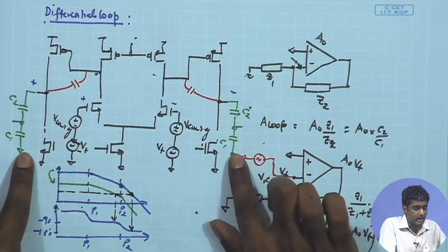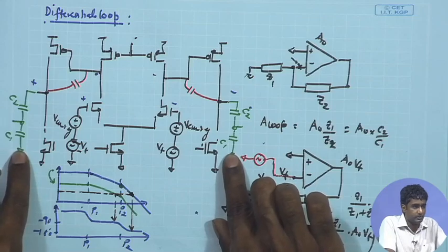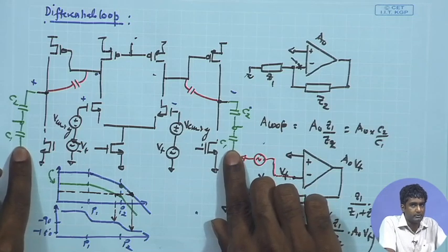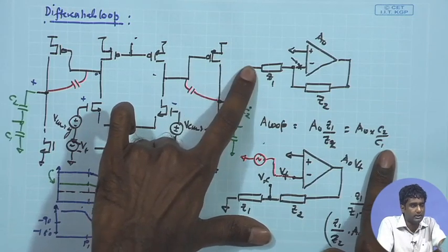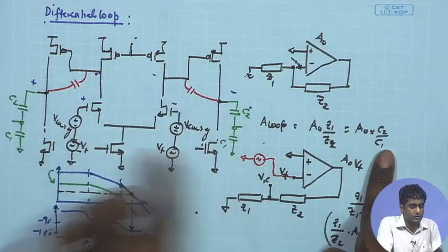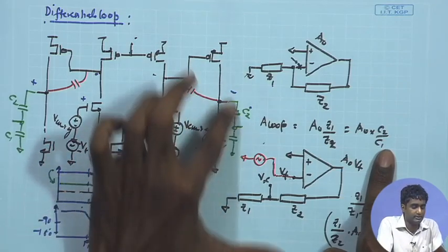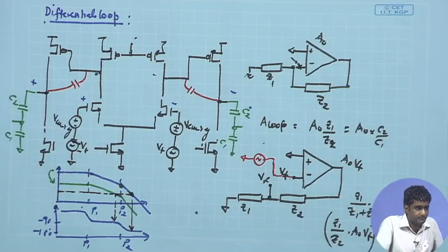So, it is not very necessary to put an appropriate DC bias over here, because this is the input point, right. In your actual circuit, this is the input point which is coming from the electrode, and we do not have control over the DC potential provided by the electrode. So, even if you put it to AC ground, it does not matter much, because anyway this is not passing any DC. So, it is not influencing the DC bias of the amplifier in any way.